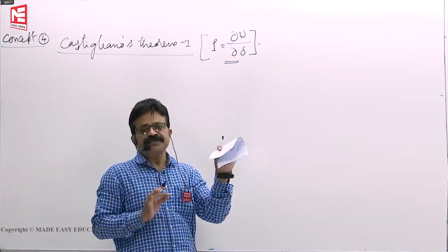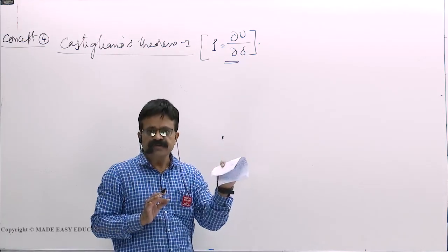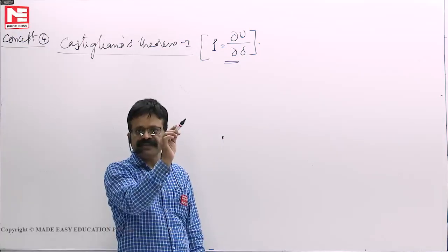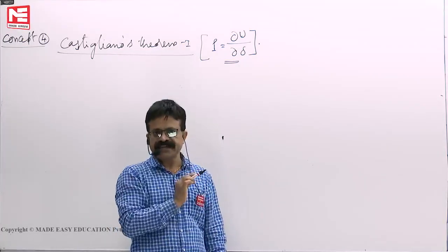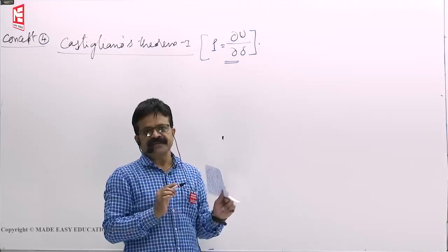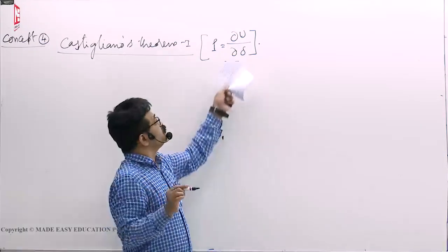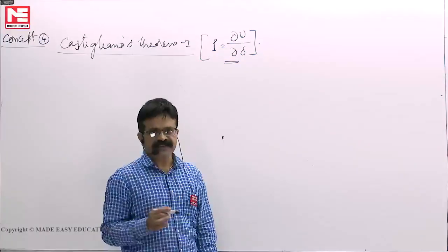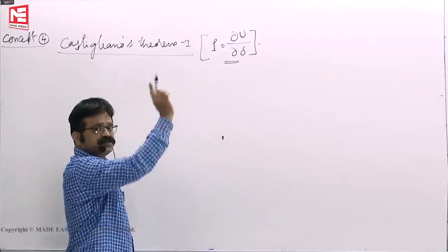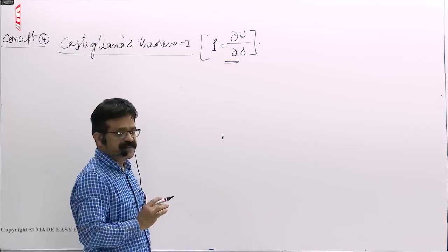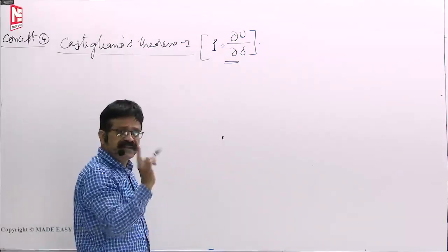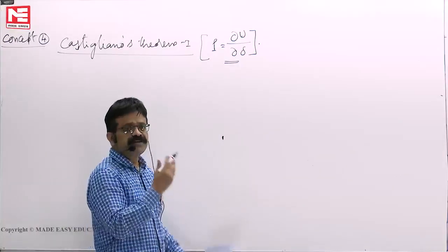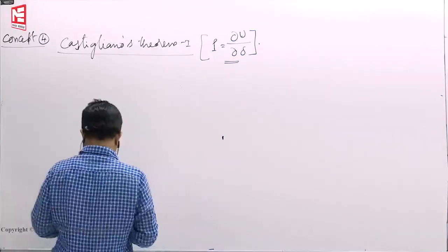At any one point, if you want to find the load, then the first partial derivative of energy with respect to delta 1 gives you load P1. Dou U by dou delta 2, you will get P2, the force at the second point, like that. So, for that, U must be expressed in terms of the displacements, and it is applicable to linear elastic and non-linear elastic structures, because this comes from the law of conservation of energy.